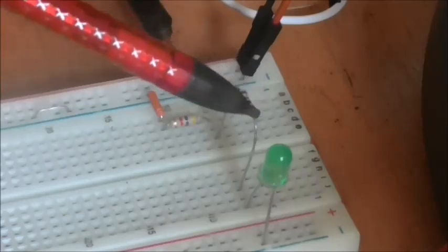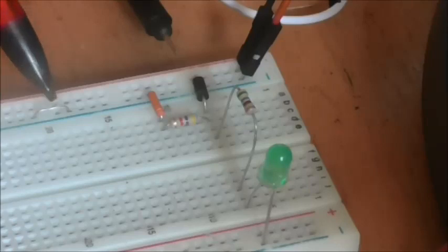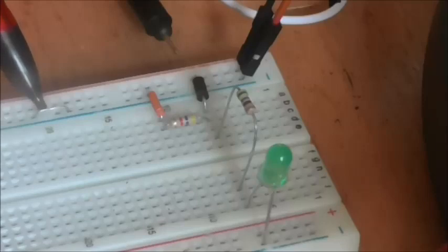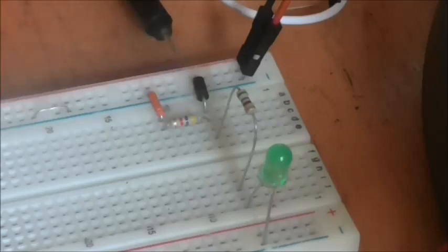We've also got a resistor here and an LED, but they're not doing anything yet. The reason for that is when we've done what we've got to do with the waveforms, we're going to see if this circuit will drive an LED. I have a test point here on the rail to put the oscilloscope probe into, to see what sort of voltage we're getting at that rail. And I have a junction here between the diode and the resistor, into which I'm going to put the oscilloscope probe after that to see what we're getting.